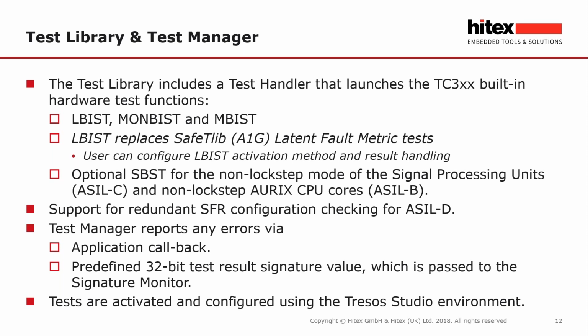There's also an optional SBST interface for the signal processing units if you wish to run those at ASIL-C, and also SBST for the non-lockstep AURIX cores that you wish to run at ASIL-B.